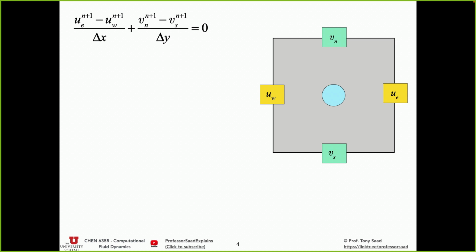It tells us that at a control volume, naturally from this finite volume approximation, the velocities there are velocities that naturally live at the faces of the control volume. Because we have freedom in the finite volume method to place things wherever we want. Remember, the location on the face is a degree of freedom. We can place variables over there if we choose to. So why not put the velocities at the faces of the control volume? So we'll keep the pressure at the cell center, but what if we place the velocities at the faces of the control volume? Could we do that? Absolutely, we can do that.